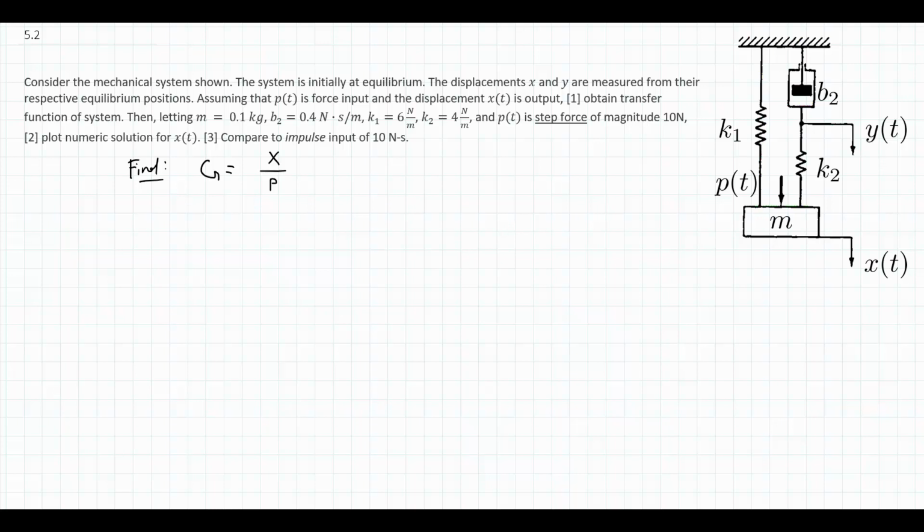It's a mechanical system, so as before, we need to start with a free body diagram, or actually several free body diagrams in this case. I'm going to start with a first free body diagram. You'll see why I'm drawing it down here in a second. That is going to be my mass. And then on the right-hand side, I am going to have the inertia of the mass. The mass has the ability to translate up or down only, no rotations, no side-to-side motion, and it is going to be defined by x. And again, we are provided with that degree of freedom, so I'll just stay with it. So x is defined as positive down.